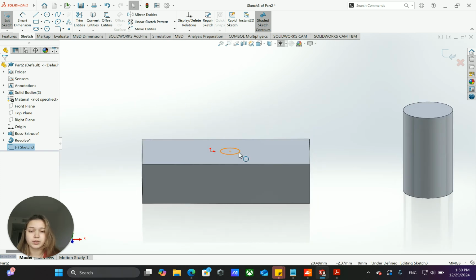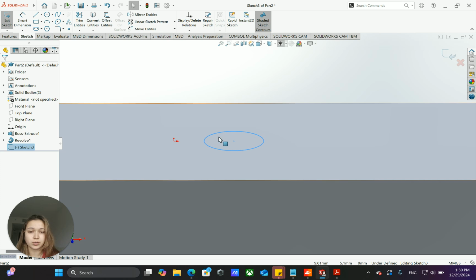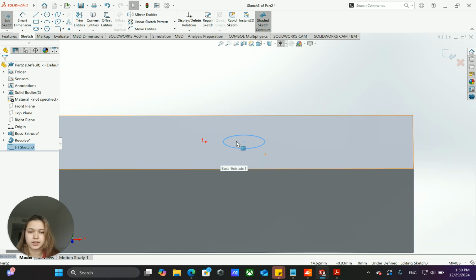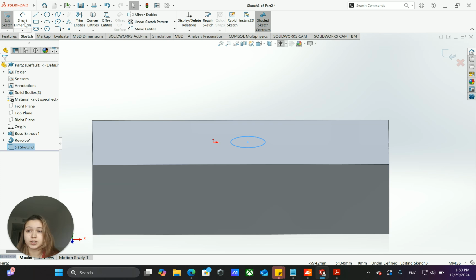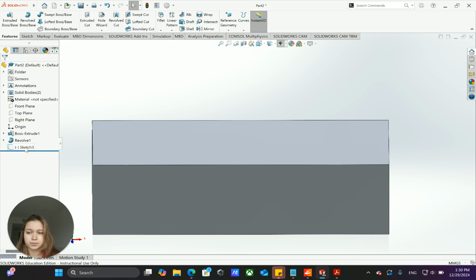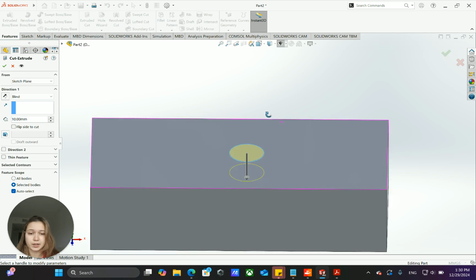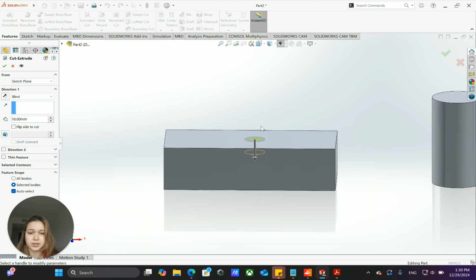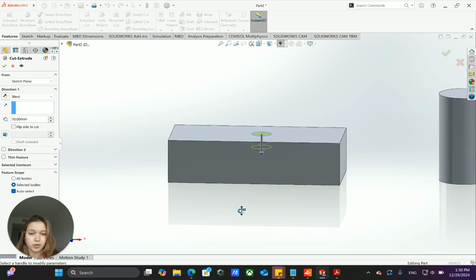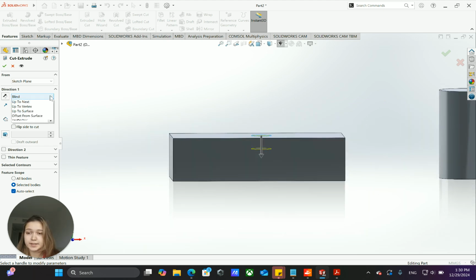What I mean by fully closed is that there are no holes, no interruptions in the sketch. Since this is a circle, there are no interruptions, and I know this. I'm going to exit sketch, click on it again, and try to extrude cut. Now, in order to eliminate the error, I'm just going to check for any intersections, also anything that might be wrong. From what it looks like, everything is fine, so I'm going to try this again.